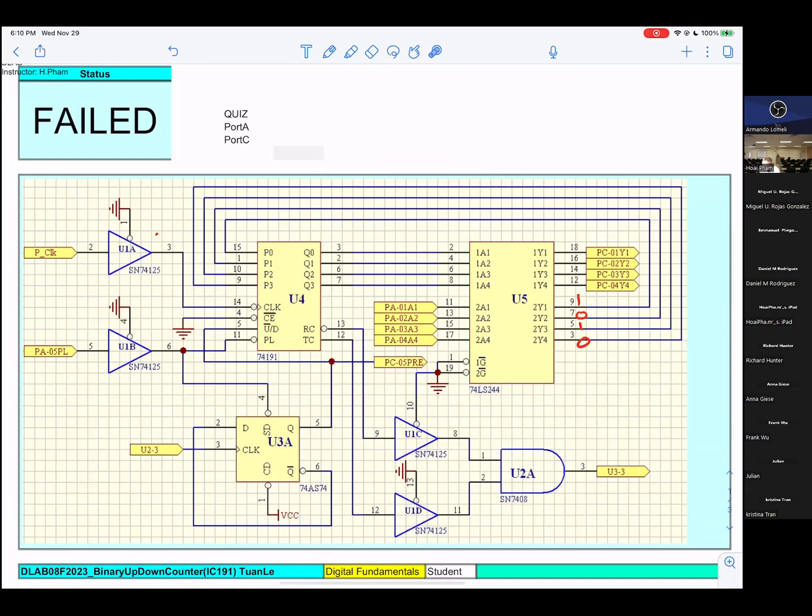Pin number 5, when you're reading, you see the bar over U and a D. That tells you pin number 5 at 0, they count up. Pin number 5 at logic 1, they count down. Okay, that's for counting. And the flag PL is active low, that means if you get a 0 here, whatever is in P0 to P3 will go to Q0 to Q3.